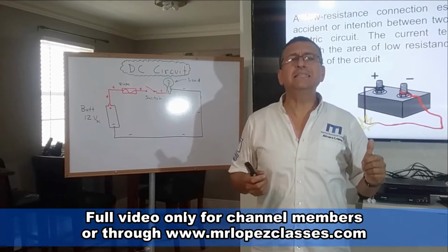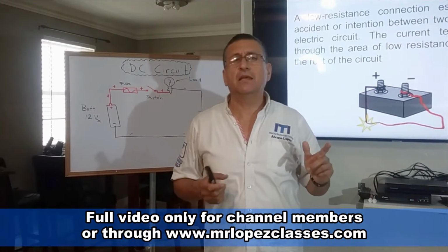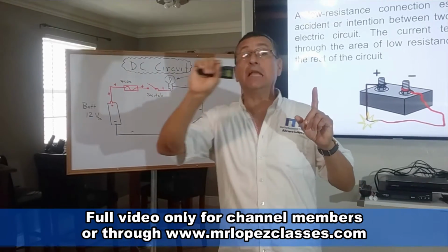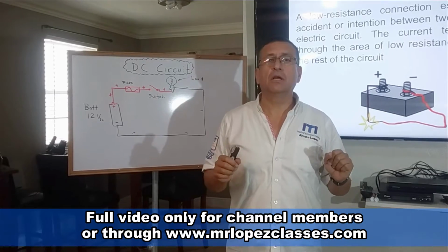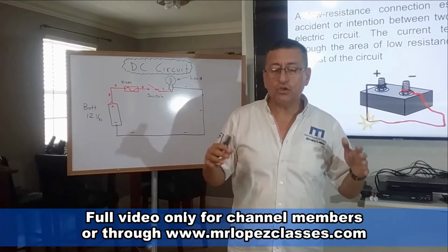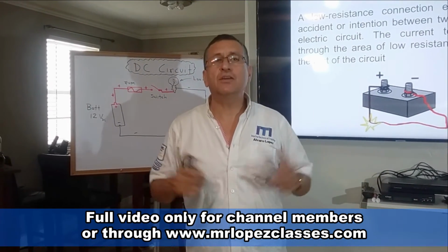What happens in the AC circuit, not DC? It's exactly the same. It's when I have one portion of the hot line connected to ground. This is a short to ground. And this is one of the most common problems in marine installations.